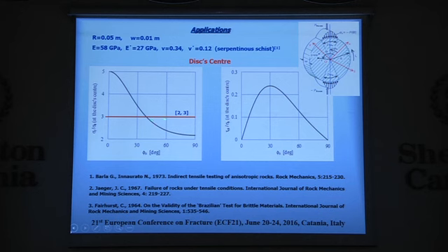And remaining at the center of the disk, we have also plotted the ratio of the shear stress over the hoop stress, again against phi0, the orientation of the external applied load. We see again that in the case of the isotropic disk this ratio is 0, due to the fact that there is no shear stress at all at the center of the disk. However, here we see that this ratio attains a comparable value, especially at 30 degrees, which is also another piece of evidence that the mechanism of failure at the center of the disk, if it is the critical point in our case, is not an easy but a complicated situation.